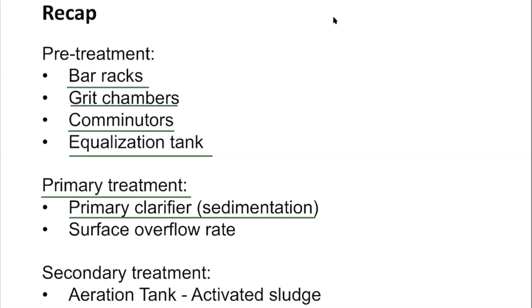So again, regarding the sedimentation, we introduced that in the drinking water treatment, when using gravity, we can define a parameter called the overflow rate, right? So overflow rate is basically the sedimentation flow rate. And that can be calculated by the flow rate going into this tank or this reactor divided by its surface area. Okay, so this is how we calculate the overflow rate.